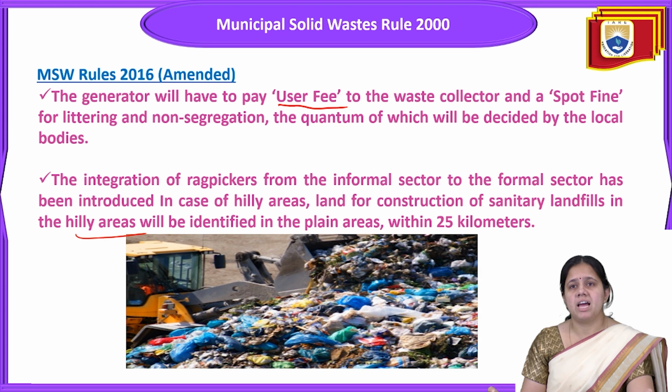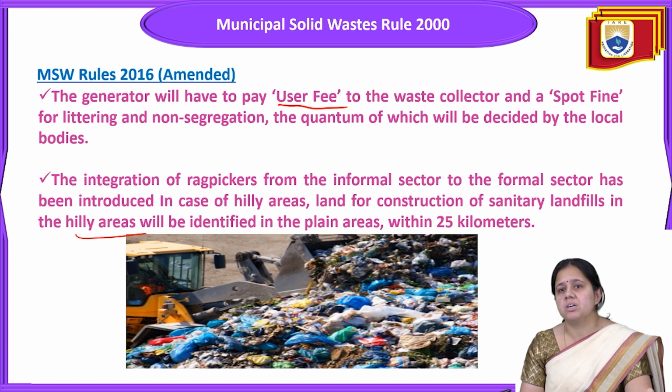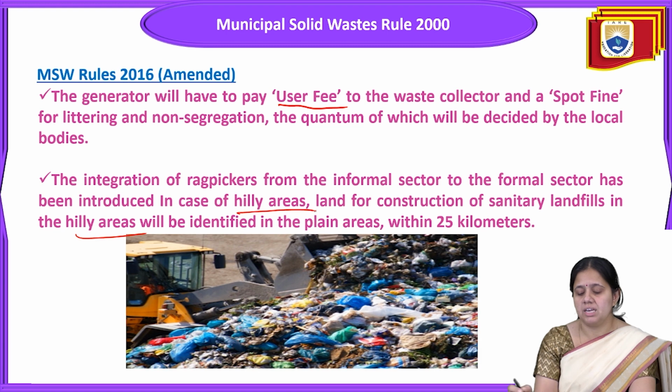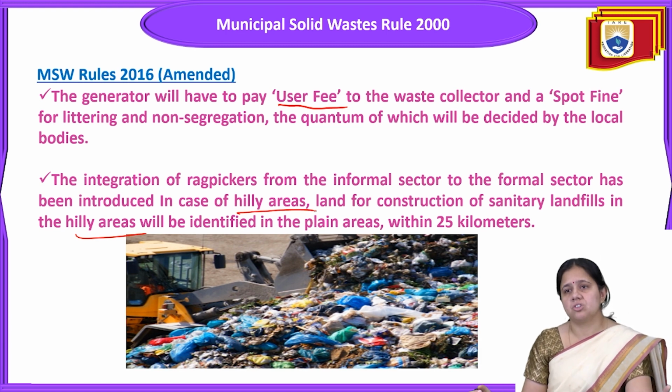So the generator will have to pay a user fee to the waste collector and a spot fine for littering and non-segregation of waste, which will be decided by the local bodies. These local bodies are basically the municipal people. And then the integration of rag pickers from the informal sector to the formal sector has been introduced. In case of the hilly area, land for construction of sanitary landfill will be identified in the plain area that should be within 25 kilometers.